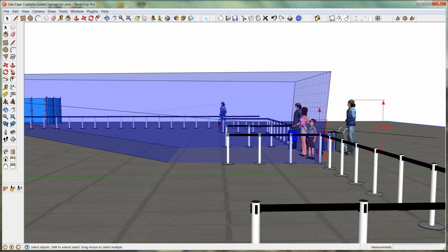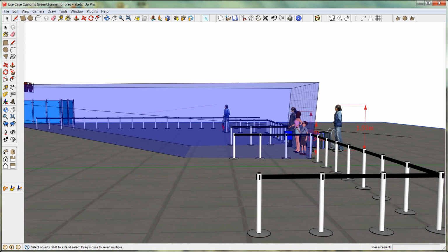But if we look again, the young gentleman there, and we see where he might exit the field of view, and just tracing it on out, right out there about the fifth tile out is where he would probably, his face would leave the field of view, because we're interested in the face and the facial recognition. And if I can go ahead and get a measurement on that in a second here, there's my tape and measure it on out, and it is about 8 meters.